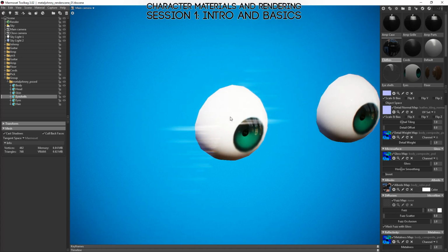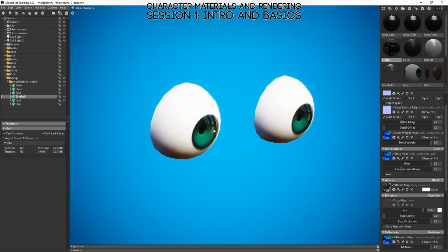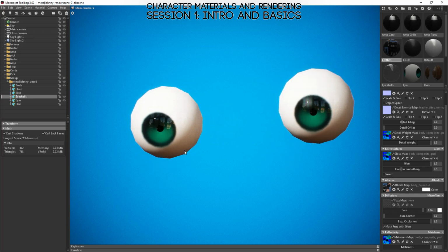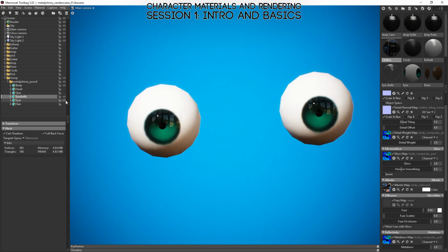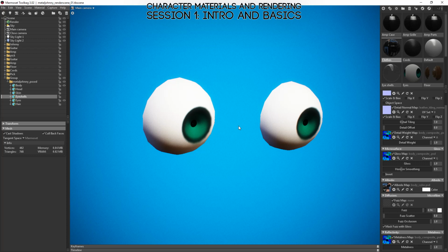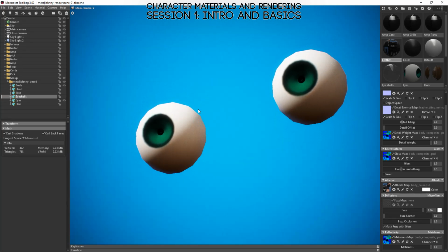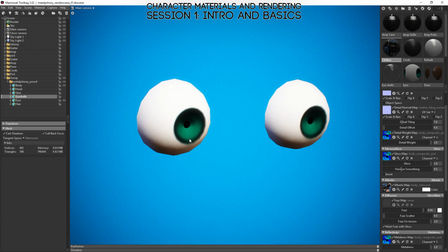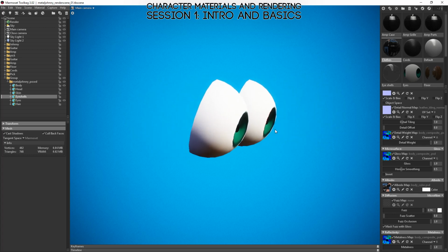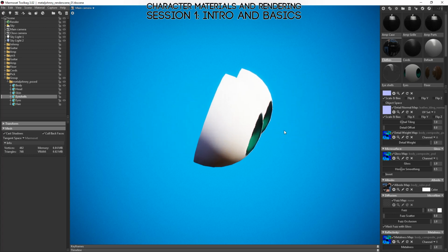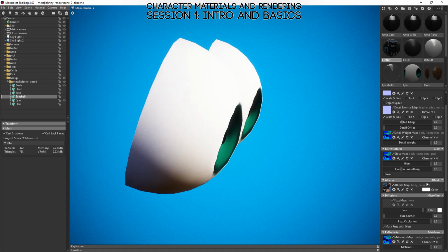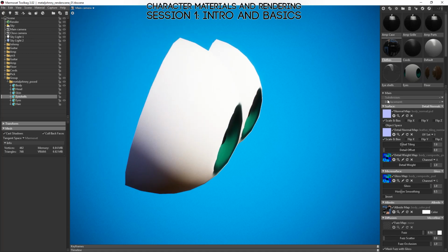Well, that's great, but it's also very difficult to get all of that into a single model, a single shader. So what I've actually done here is I've made the eyes in two separate pieces each. One part is the inside of the eye. It doesn't have any reflections on it. It's just diffuse shading and a little something to make it look like it's refractive. So this is Parallax Mapping.